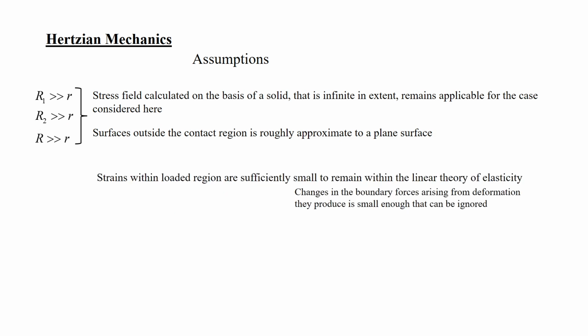The second consideration is that strains within the loaded region are sufficiently small to remain within the linear theory of elasticity. That is important, because whatever we are discussing, the stress-strain relation, Hooke's law, where the normal strain is epsilon_xx equal to del u by del x and so on, all fall under the linear theory of elasticity. Therefore, we have to assume here that the strain within the loaded regions is very small. That is important.